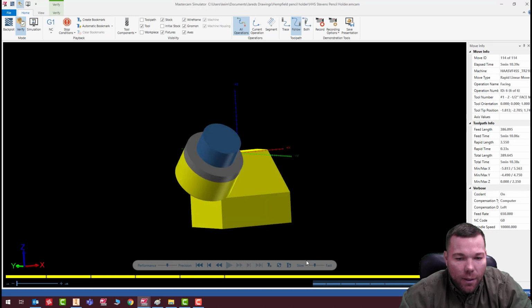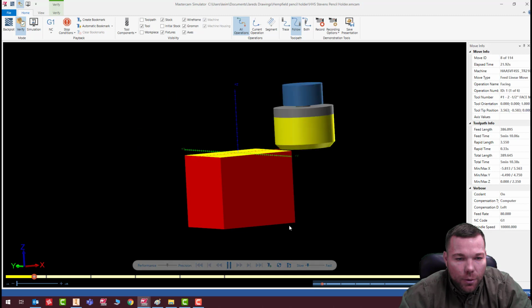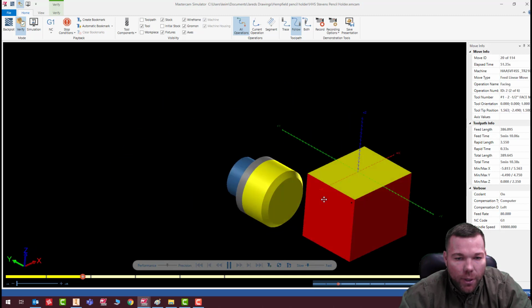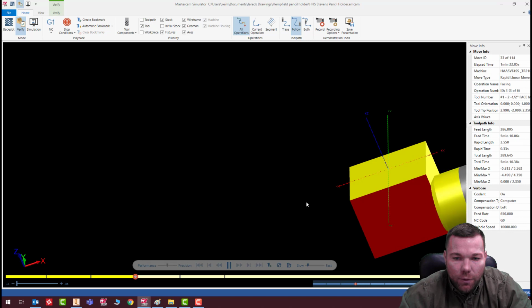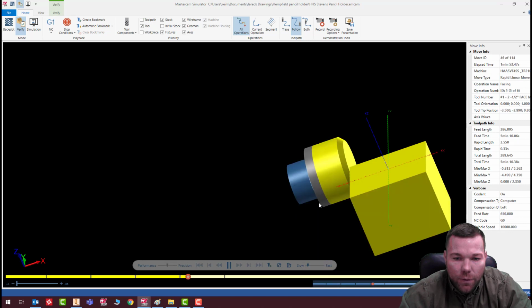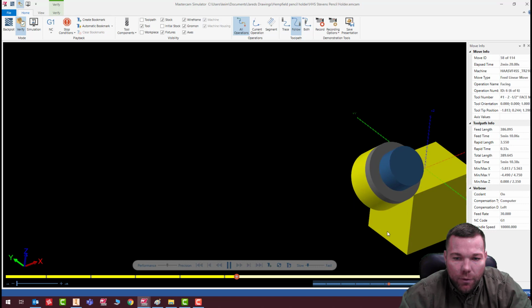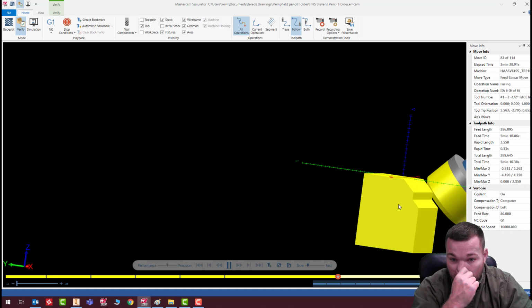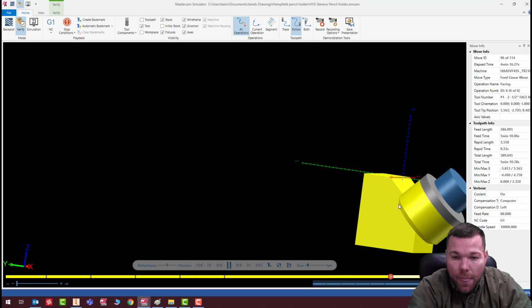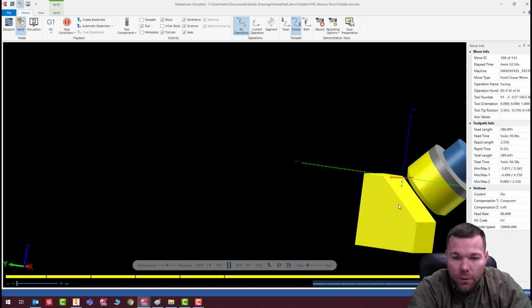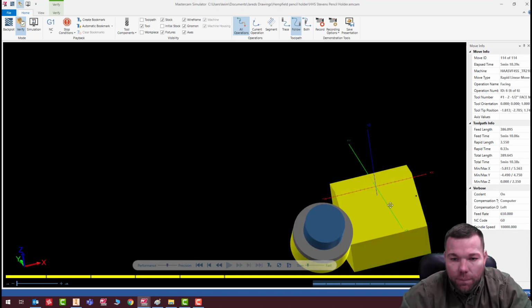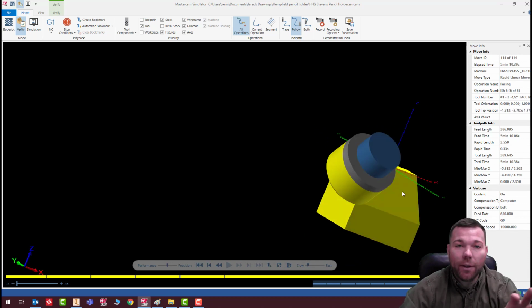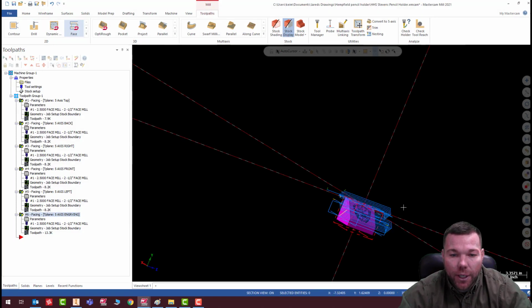I'm happy with that. Let me slow it down and go through it just a little slower just to make sure. Just facing the back, side, doing the finish, front, finish pass, left, finish pass. And it's cutting the angle on, finishing it, and that looks good. All right. So we have all sides of it finished, or faced, not necessarily finished yet.